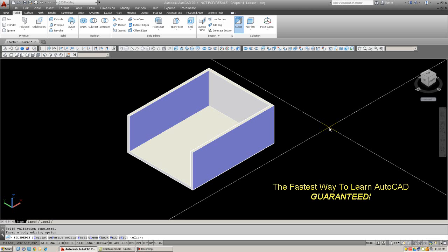And you'll see this type of command also in other software like CATIA and Pro Engineer, very popular in solid modeling. Alright, so practice these two commands. You should have already practiced Revolve and now practice Shell. And we'll see in the next lesson. We're going to cover some additional commands. We're going to go right down the list. We're going to cover Taper and Loft, and try to squeeze in Path Extrusion and Sweep. And if we can do that, we'll reserve the third lesson for some examples. And if we don't cover them all, then we'll put one of these commands into the third lesson and then do some examples and get you to practice all this.